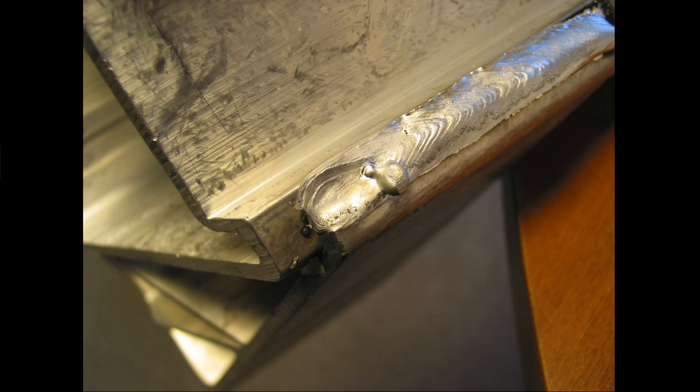Here's a termination, and I always like to put this out there. It's a crater. It has no crack. It has very little oxide in it, even to be concerned about. It comes to the edge of the weld. It's not exactly the right choice, to be honest with you. You would always start on an outside edge. This is the outside of the component, but you would always start on the outside edge and weld in.